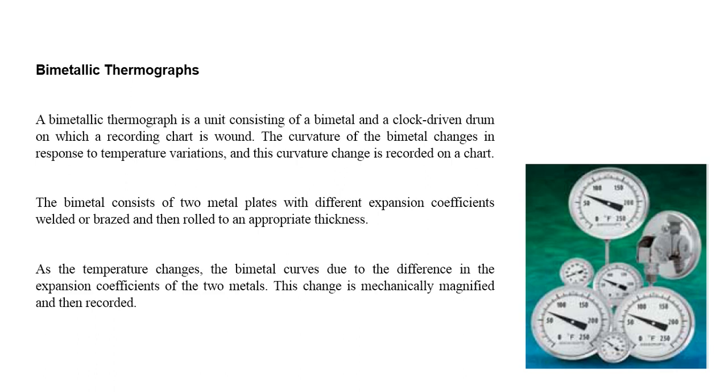The next type of measuring instruments are bimetallic thermographs. They consist of a bimetal and a clock-driven drum on which a recording chart is mounted, as shown in this figure. The curvature of the bimetallic strip changes in response to temperature variation, and this curvature records that change.